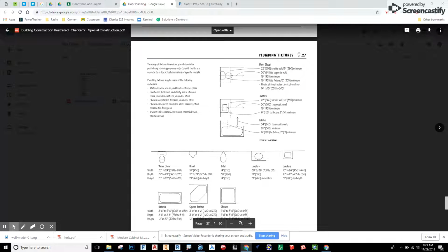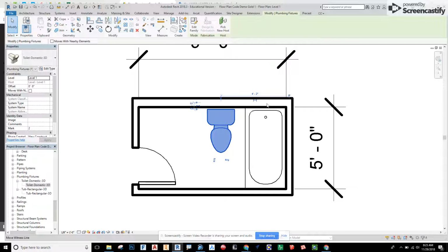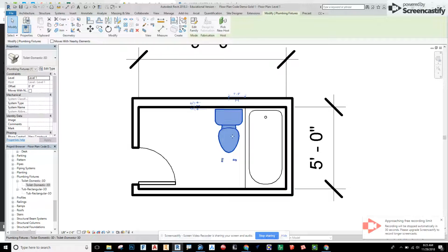So I'm going to go over to Revit again, and we're going to make sure that this thing is not less than 12 inches from the edge. So I'm going to drag my dimension over here. It's already center. It's at 1'5". We could make it the minimum right now. That's 12 inches center. It looks rather close. So we could say, you know what, let's just make that a nice even 18 inches,